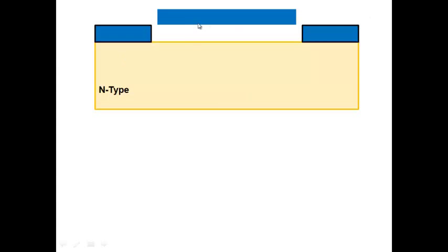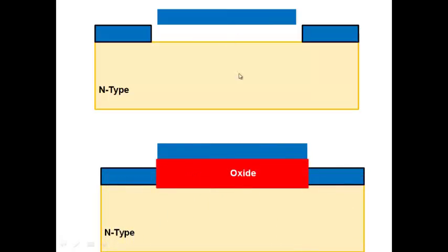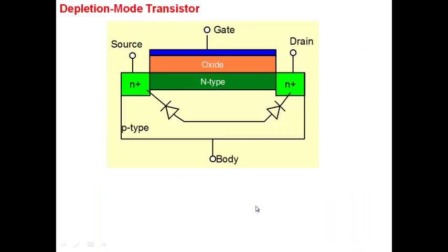All right. So what we have said is the field effect transistor is here. We can't let a plate hang in the air like this, so it's more convenient to have a dielectric in between. In silicon, the best dielectric is silicon dioxide itself. So you get a metal plate, the gate, here, oxide here, and a semiconductor here. What you are seeing is a field effect transistor based on metal oxide semiconductor. So it's a MOSFET.